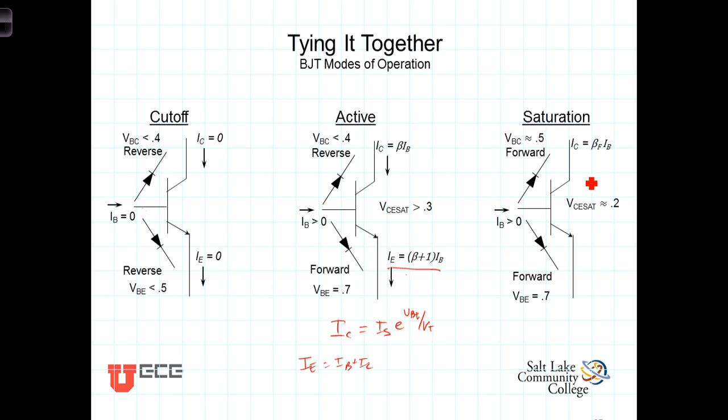And we then stop thinking of the transistor as being two separate PN junctions. We just think of it as being a continual piece of silicon with a surplus of electrons. At that point, the transistor is said to be saturated, and the voltage from the collector to the emitter, VCE, becomes relatively constant at what is known as the saturation voltage, or VCE sat.